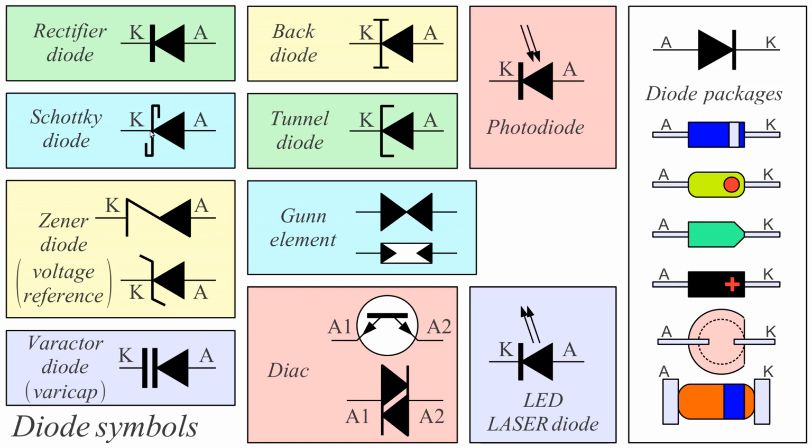The cathode, the semiconductor side, is marked on its package. On its package, the cathode always has a ring or a dot or some kind of shape of the package, or a plus sign, because as a rectifier they provide a plus sign, or a cutaway on LED packages, or a ring on SMD diodes. So this is always the cathode is marked on the diode.